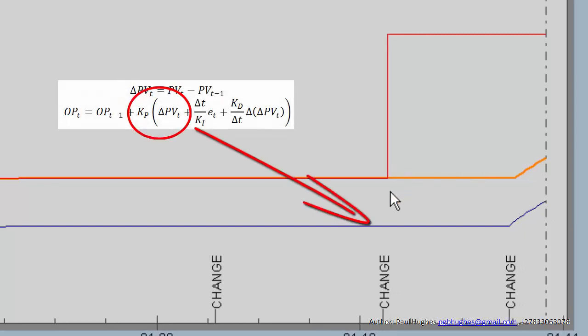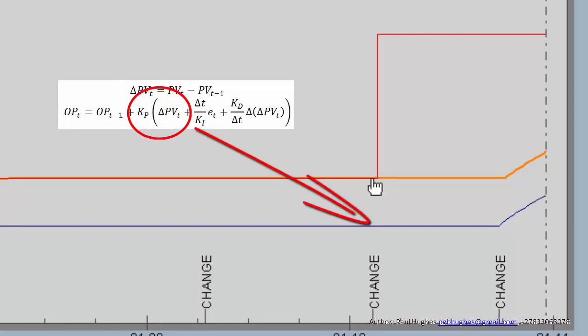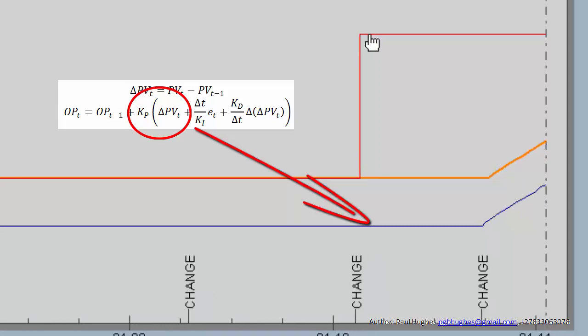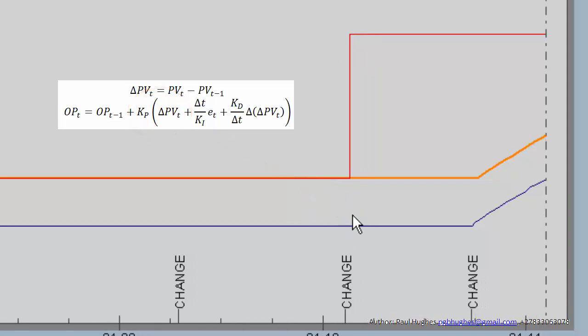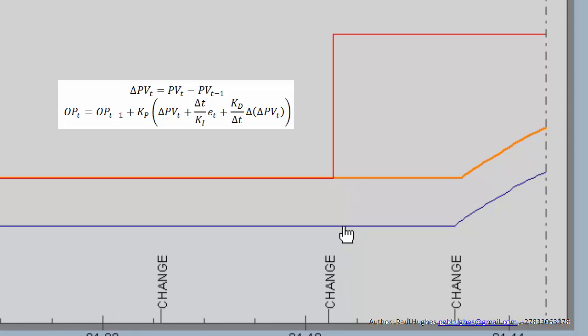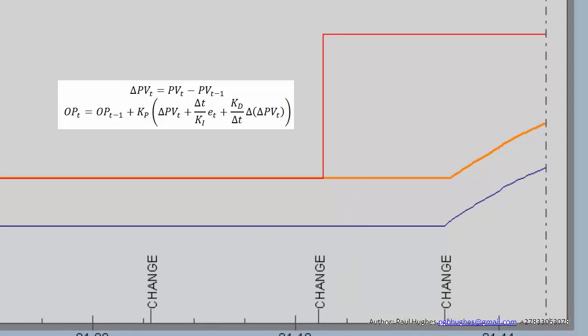What I'm trying to demonstrate here is that with this particular set point change, because I'm not using the error in the proportional term, there's no kick in the output. So one would normally expect to see, when we do the set point change, this kick and then it comes down like we would before.